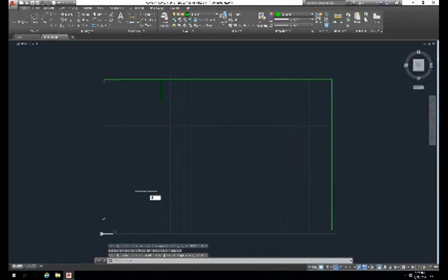Oh, something happened. Offset 4.12. Oh, I didn't click, so I've got to left click with the mouse. See, it still says select objects to offset, but it's going to be doing a different size, or same size. Now, actually, it asks me. So the top projection has the total width of 2.3. 2.3. Enter.